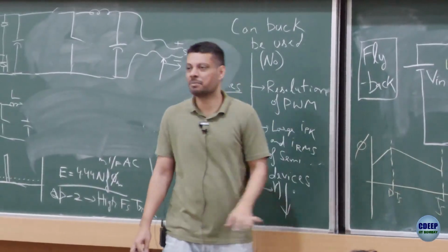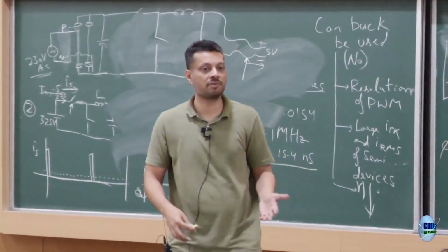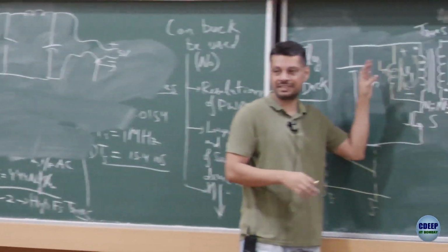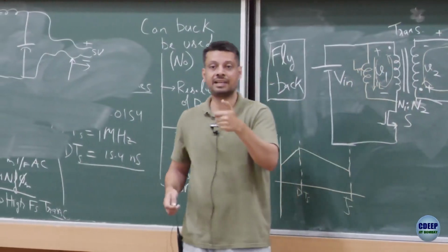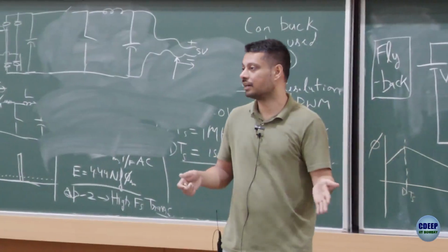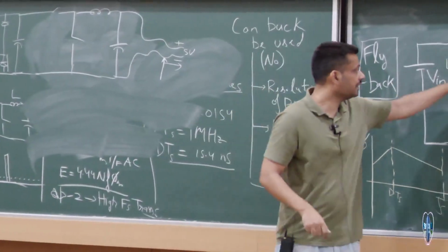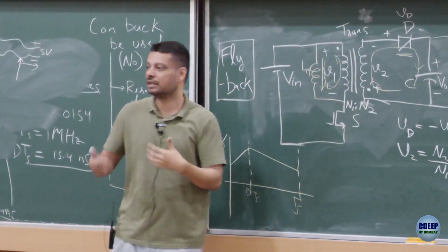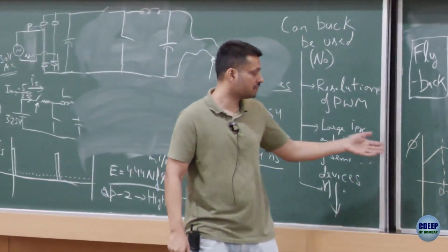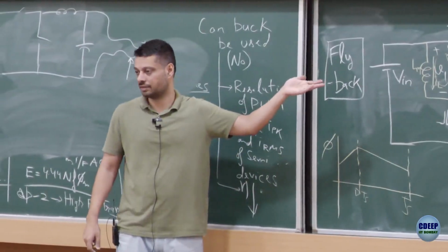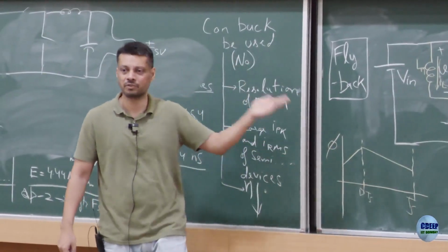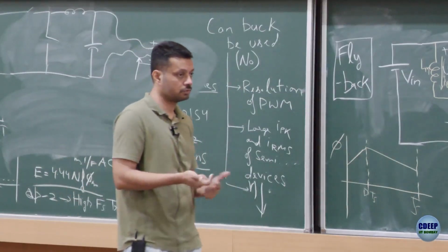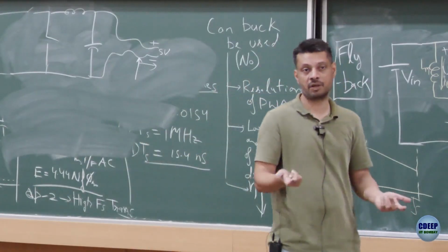In this case, why we are drawing the flux waveform, why we have not drawn it before, is that before it was very clear there is a separate inductor with its own current. In this case, this inductor is not there physically, right, it's merged. So if I tell you to physically observe the inductor current, you cannot, because this is inside. If you measure this current, it will be this plus this current, you will not get the transformer current, and therefore in a lot of books, a lot of explanations, people would explain using the flux instead of the current, and that's why this flux waveform has some significance here. But nevertheless, the flux waveform was there in the buck converter also, boost converter also, because there is also an inductor with a core with N number of turns.